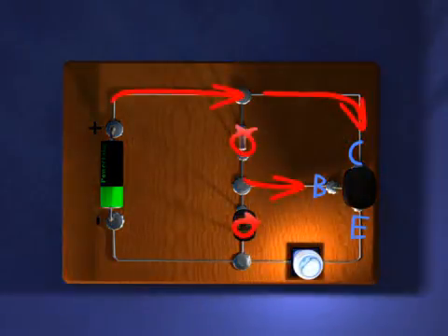When ambient light decreases, the resistance of the photoresistor increases, which means that eventually the voltage rises to a level that allows a flow of current across the base emitter junction. The light bulb will light up because a high current is flowing right through the collector emitter junction. That way, a low current through the base emitter junction will control a high current flowing through the collector emitter junction without movement of mechanical parts.